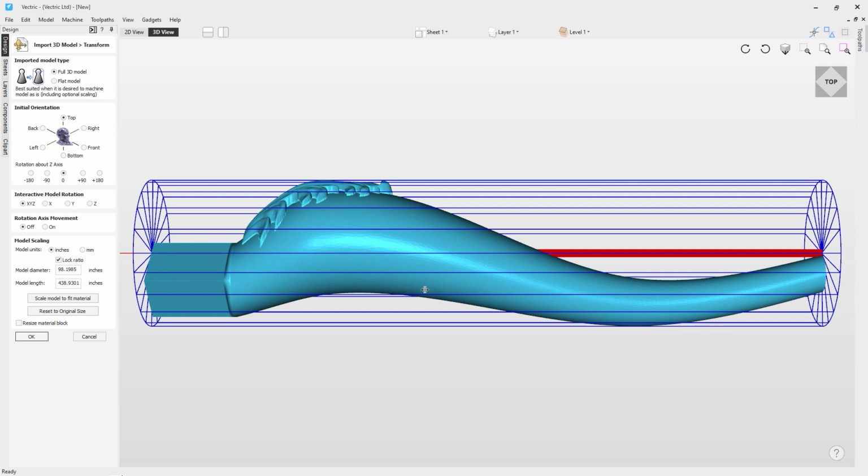Now here's another example of when we should try to get rid of any undercuts, or try to align our model better so that we can alleviate as many undercuts as we can. It's important to remember that for some models it will just be impossible to do that. By the end, you may end up having to remove it by other means, maybe after the part is finished, or by breaking up your part into several different pieces. But we want to try our best to hide that rotational axis inside the component. So let's have a look at doing that.